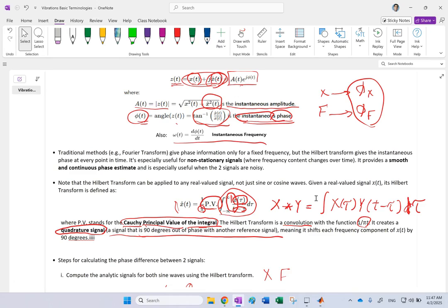So when you pass the entire signal to it, all it gives you is a frequency plot used for all time points. But the Hilbert transform does it for each and every one of the points. So it calculates the phase or magnitude or frequency instantaneously, not for the entire data.